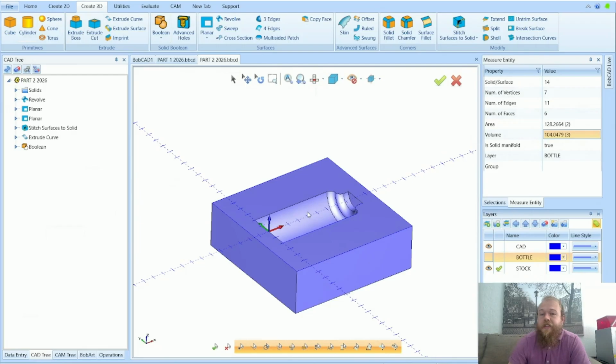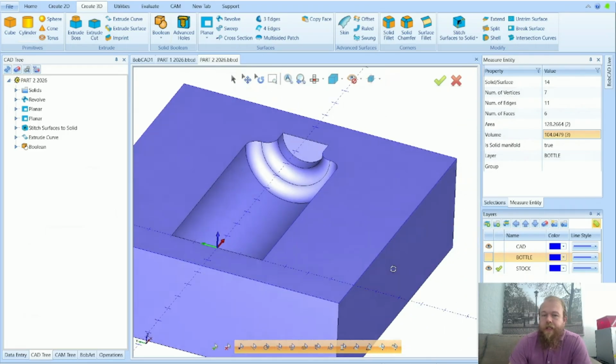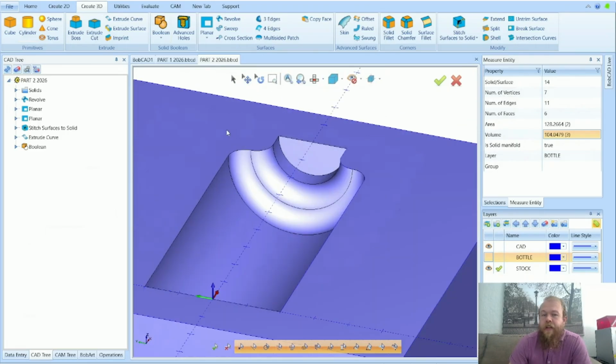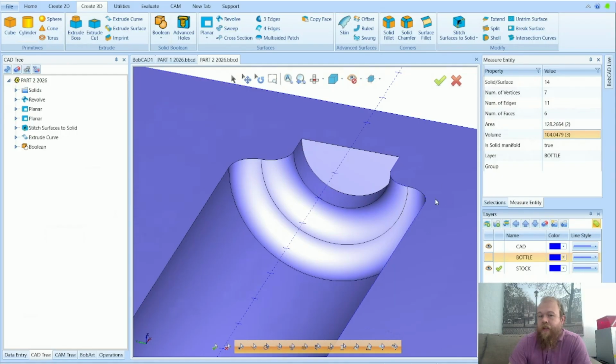And this is going to be in mill 3-axis in a later webinar, so that we can rough inside of this area. And then in the 3-axis milling, we'll use a planar tool path with a ball end mill. The ball end mill will move X, Y, and Z simultaneously to follow along these curved surfaces.